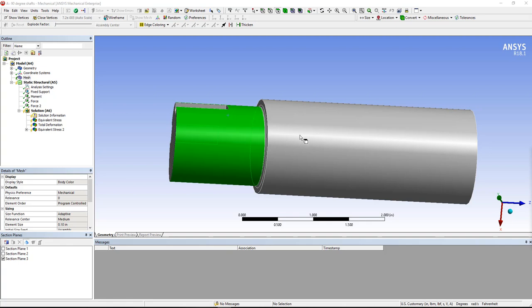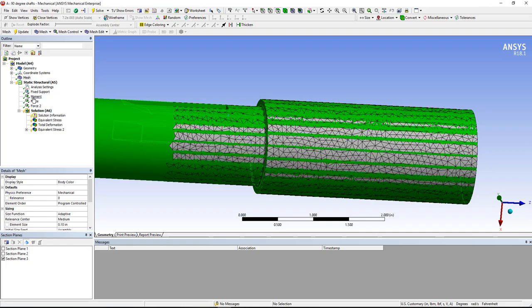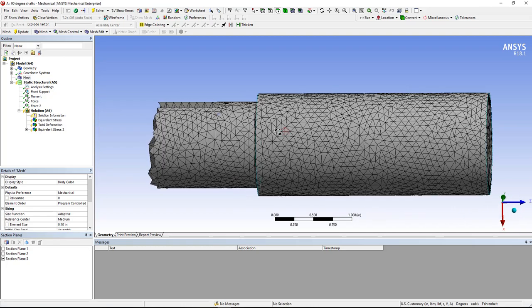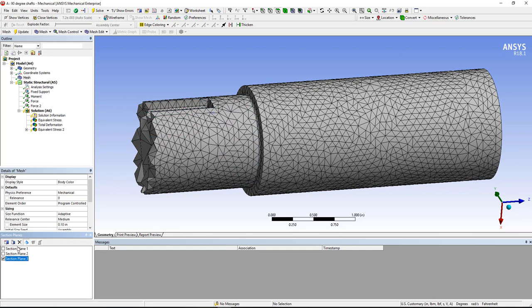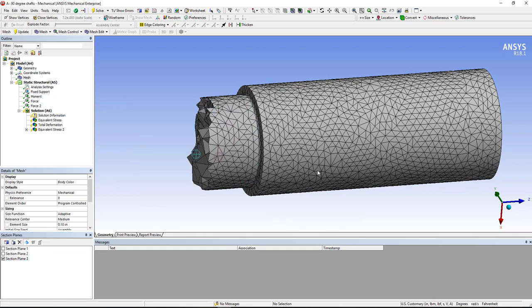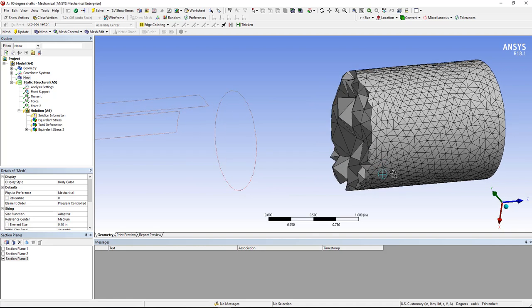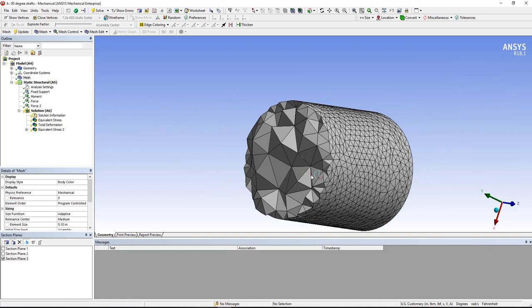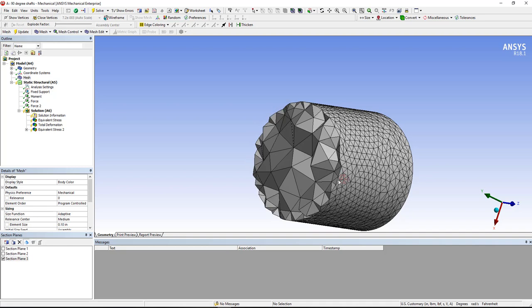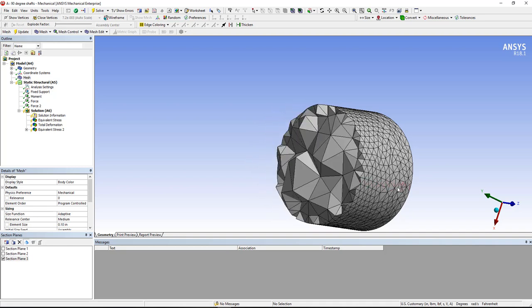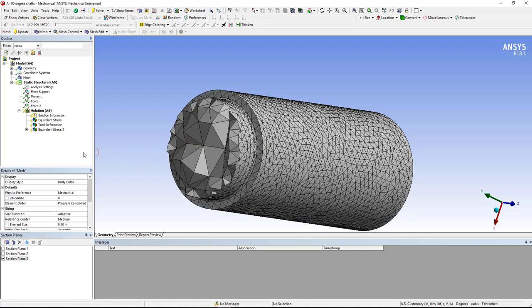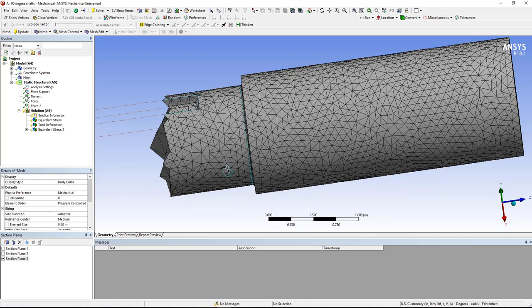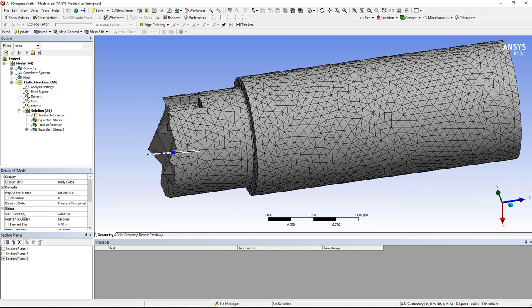So you're going to try some of these different things and get some of the general mesh you want, and you can do that right there from the sizing process. And let's edit our section plane again, so we can drag this back and forth. So I'm getting a finer mesh on the surface, fairly coarse in the middle. I don't care a lot about that region, but I'd feel a little more comfortable with a bit finer mesh.